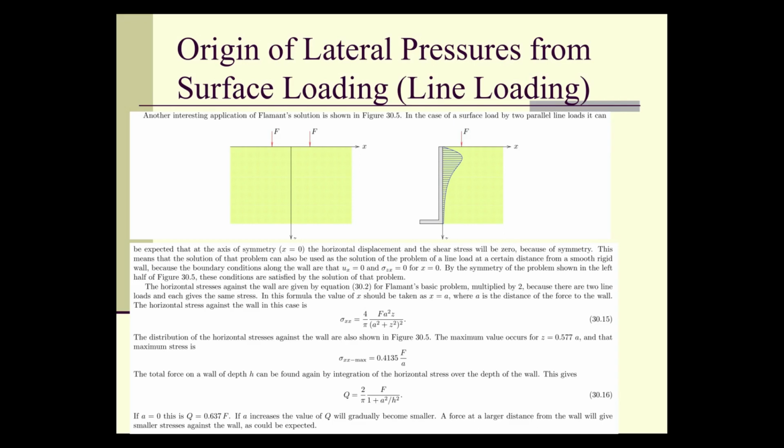And what he discovered was that there were two competing theories at the time, one based on Coulomb theory and one based on theory of elasticity. The theory of elasticity was a better way of predicting, if you apply the loads, for example, like this, where we have a line load, than using Coulomb theory. And it's been pretty much the rule ever since.